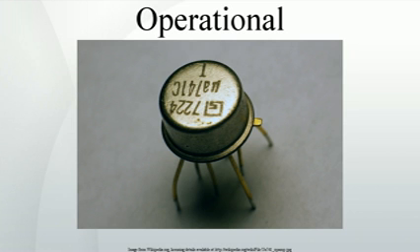The circuit designer can implement this compensation externally with a separate circuit component. Alternatively, the compensation can be implemented within the operational amplifier with the addition of a dominant pole that sufficiently attenuates the high-frequency gain of the operational amplifier. The location of this pole may be fixed internally by the manufacturer or configured by the circuit designer using methods specific to the op-amp. In general, dominant pole frequency compensation reduces the bandwidth of the op-amp even further.